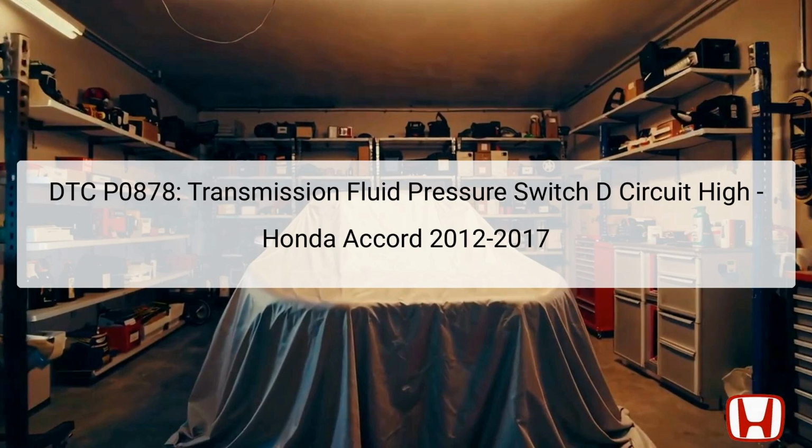The transmission fluid pressure switch D plays a crucial role in monitoring the hydraulic pressure required for proper transmission operation. It is located within the transmission housing, wired directly to the powertrain control module, PCM. When this switch fails or indicates abnormal conditions, it can significantly impact performance, leading to gear selection issues. Proper diagnosis involves utilizing the Honda Diagnostic System, HDS, to retrieve stored codes and verify the health of the system prior to performing physical diagnostics.